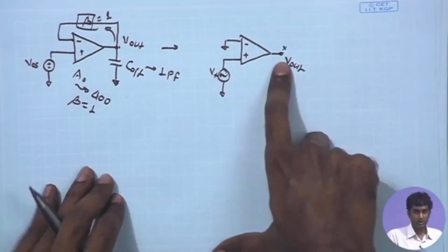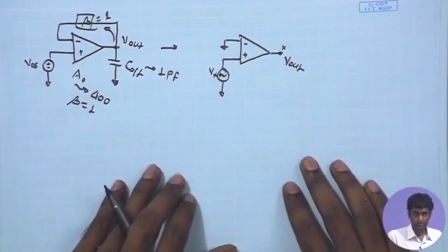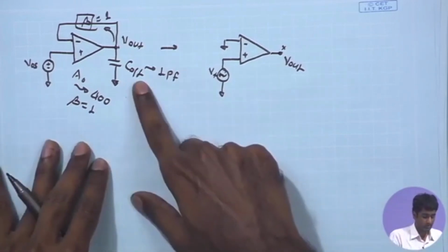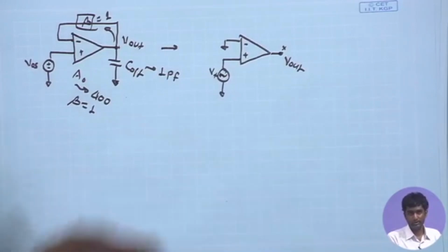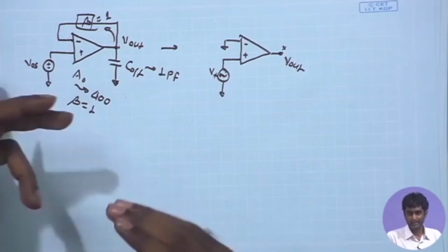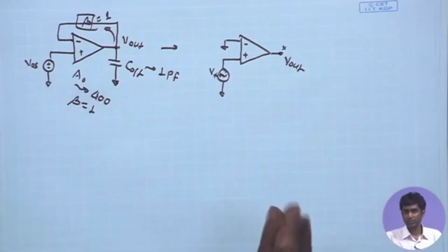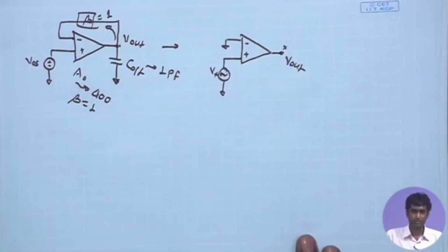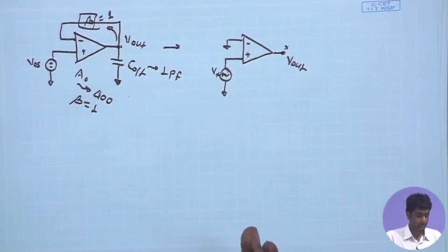And now, if I look at the loop gain and the corresponding bandwidth that we can get for a stable operation, we know that this is a sufficiently large capacitance as compared to the parasitic capacitance. So, while discussing the comparator, we discussed that the overall pole is going to be determined mainly by the parasitic capacitance CGD and its Miller multiplication, and we did not consider a significant load capacitance present. But now we have this large load capacitance present for the closed loop scenario, and then we have to see what is the resulting gain bandwidth product.